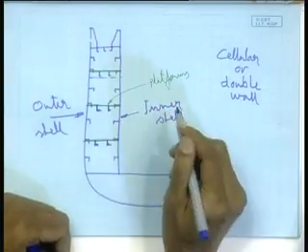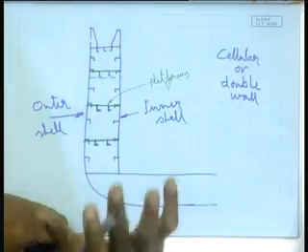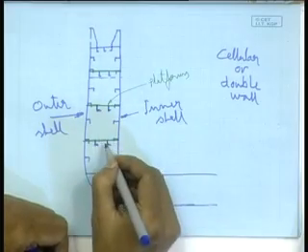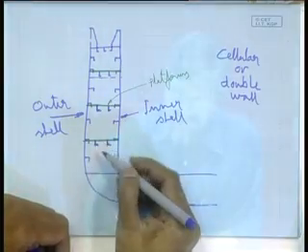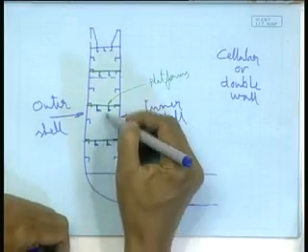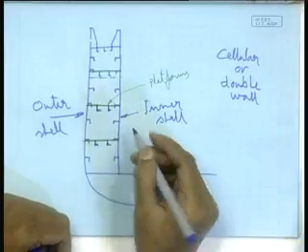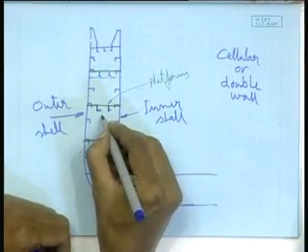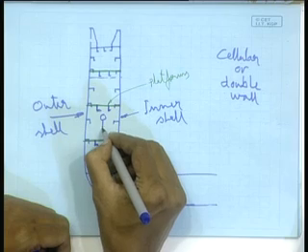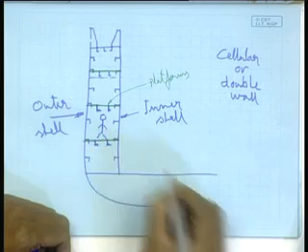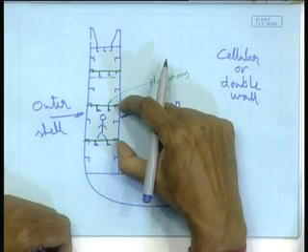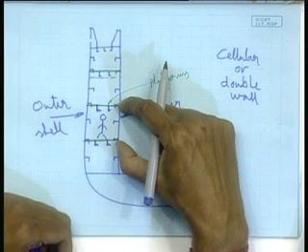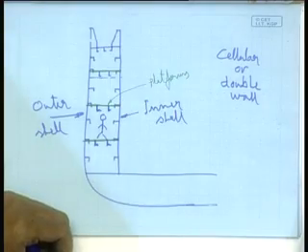for maintenance. It is simply for maintenance, nothing else, because if this is provided, then a person can walk through all along and do the inspection and maintenance of this. The spacing between these platforms should be such that an average height person can comfortably walk through.